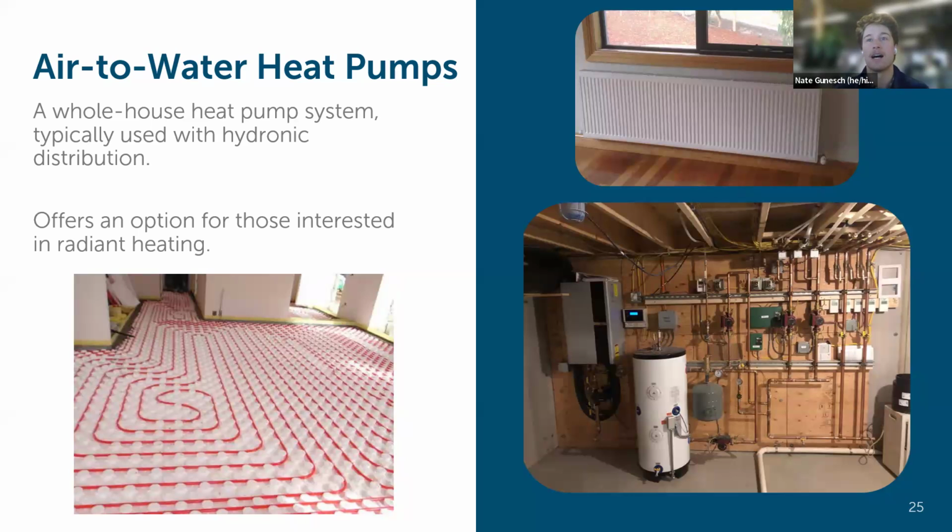It's true that any kind of hot air system, you could feel those drafts, right? If you wanted to think about specific products that can help cut down on those drafts, those ceiling cassettes sometimes work well for that. I think ultimately, if you are sensitive to that moving air, which is one of the principles of HVAC design, right? We think about our comfort in terms of dry bulb temperature exclusively, but that's not the only thing that matters to us, right? It really matters how warm our surfaces are around us. It matters if there's a differential on either side of us, and moving air really impacts how we experience heat. So if you're quite sensitive to that, a radiant system is probably the best system for you.